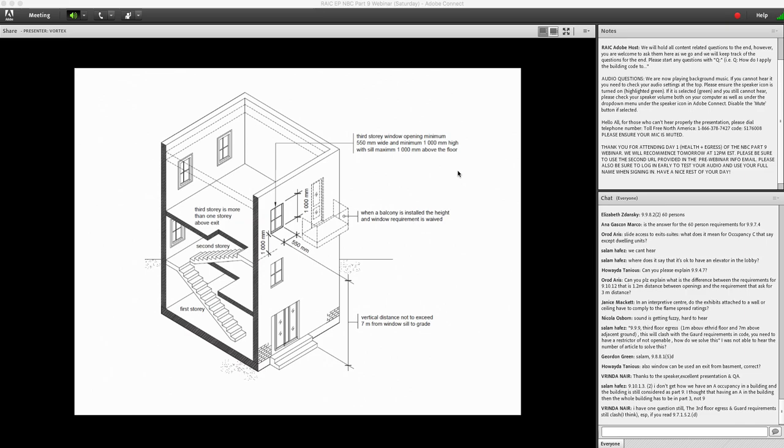What is the difference between a fire block and a fire stop? These are two defined terms in the code. Fire blocks are typically applicable to concealed spaces in a building. The idea behind fire blocking and fire stopping is to limit fire spread to other areas in the building, for fire blocking through the concealed space, for fire stopping through openings in the fire separation.